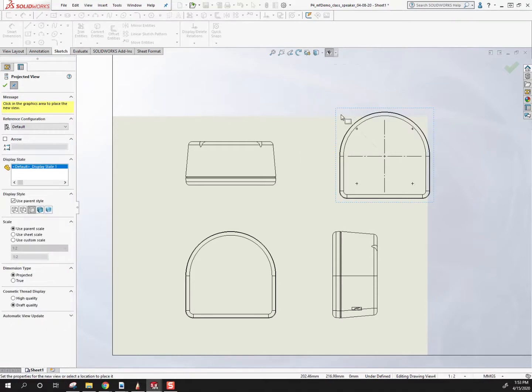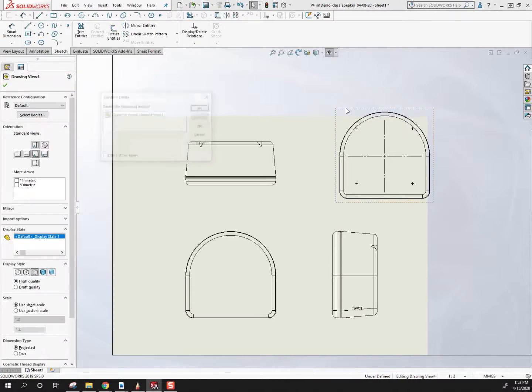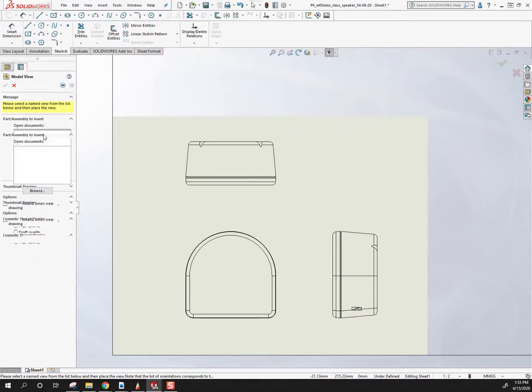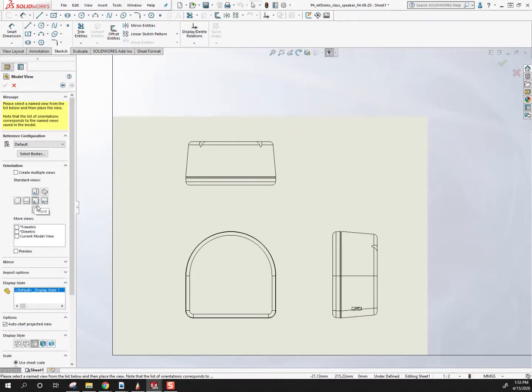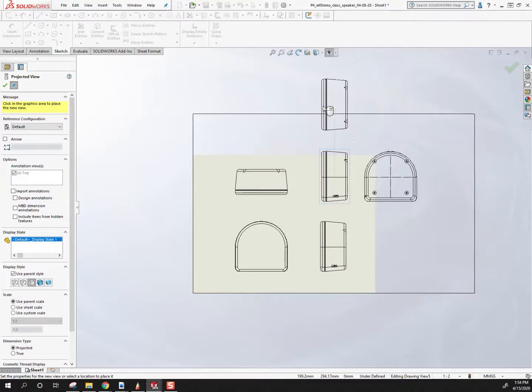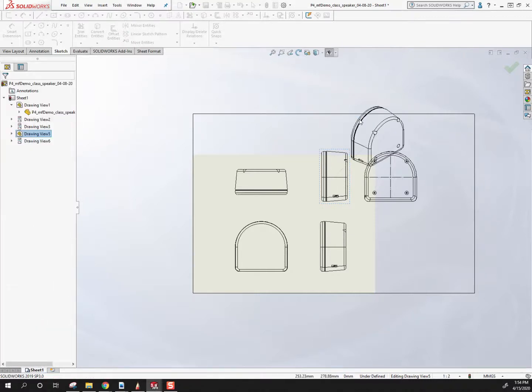Yeah. If for some reason the first view you click is not the front view, or if you want to look at the settings that I have, let me escape out of here and delete this. Look at this icon here, the set on the left side. You want to make sure the front is pressed in. Or if for some reason you built it so your object is facing to the right, you can always click on the right view, and now when I click, it starts with that right view. So you can change what's shown with that starting. But then, of course, everything can then be generated from that first view that you place on the page.